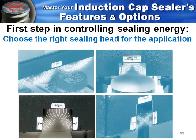The final sealing head on this screen shows a combination of our standard tunnel and our deep tunnel. So we've increased the height profile here, and this is particularly important in some of the newer style closures that you see come out. Think about the upside down products that you're seeing, maybe an upside down ketchup bottle. And those products have a little bit larger diameter closure, usually with a flip top design, and have a foil in it. So that foil is recessed quite a distance, but we have the ability here to heat both from the top and from the side.